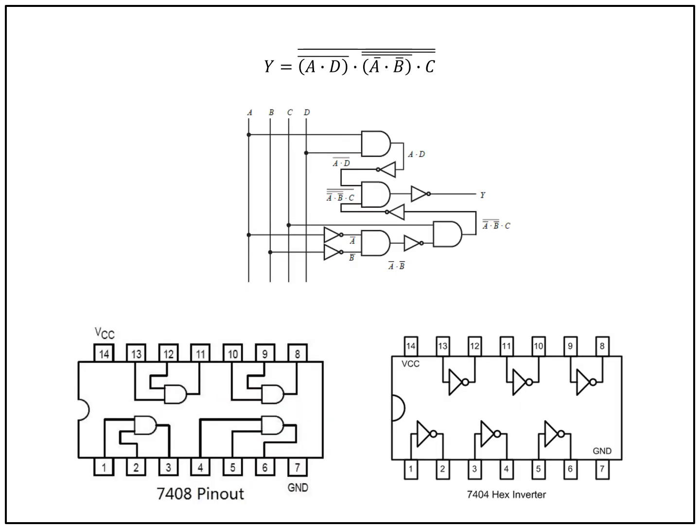Now to realize the digital circuit that we constructed, we would need two integrated circuits, the 7408 and the 7404. Notice that the first, the 7408, has 4 AND gates, exactly as what we need in our circuit. And the 7404 also includes 6 inverters, exactly as many inverters as we need in our circuit. So these two integrated circuits would be enough to realize the digital circuit for the security system.